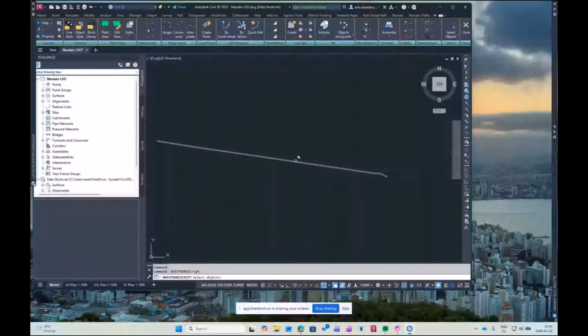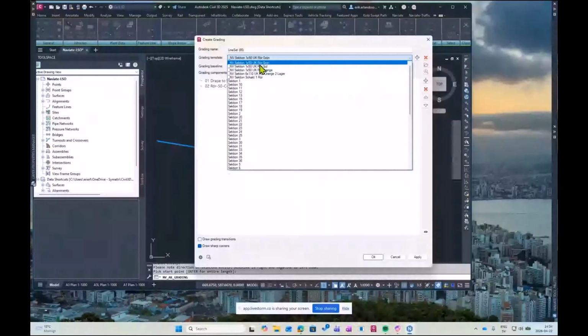And now I want to add a line set that represents the trench. And I've made one of these templates. So if I go to create, select my 2D line here, press enter for the whole length, and then I change it to my section and trench.